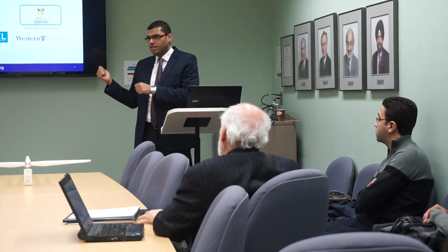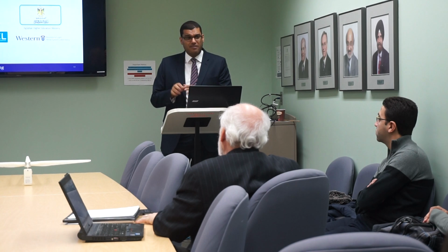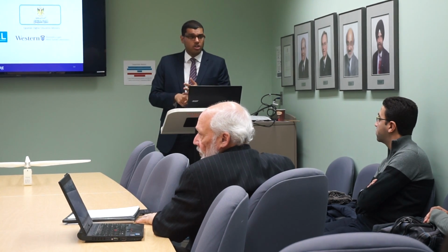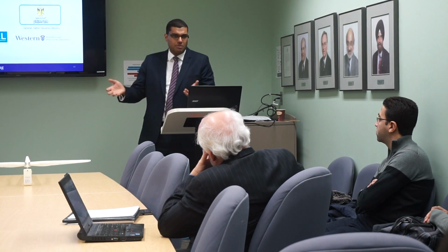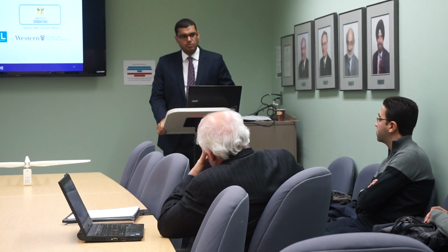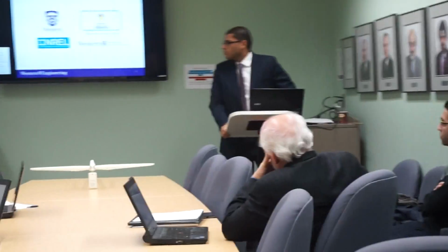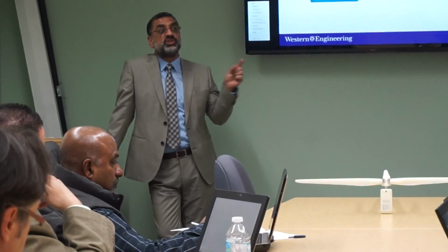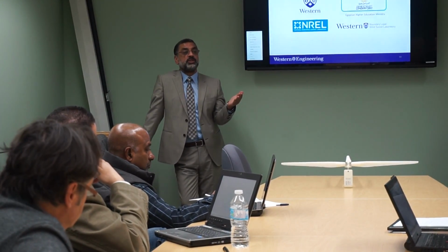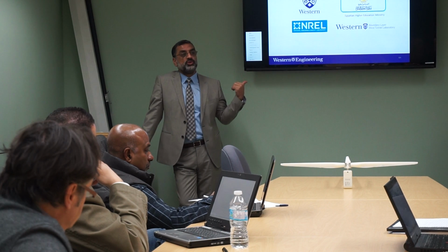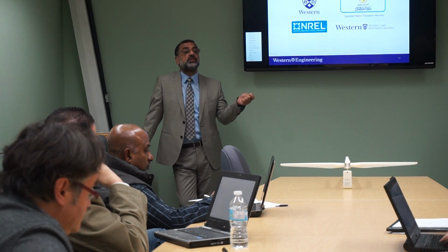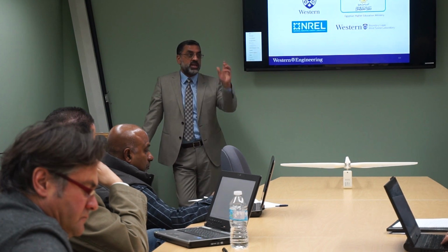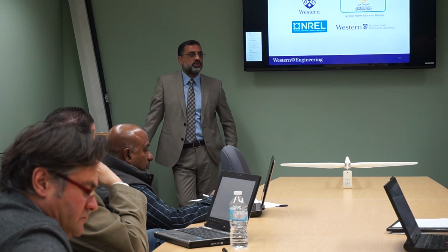Although in our study, I maybe didn't mention this in the presentation, we have done two analyses. We have done analysis in working position under working load, but mainly our analysis was in the extreme case, which is the parking position. Just a point of clarification: the operational loads for serviceability are the published data. What Ahmed produced was for the ultimate limit state. So they shut down. When the wind speed is high, you don't run the turbine, it has to stop. Yeah, so it's a park position.